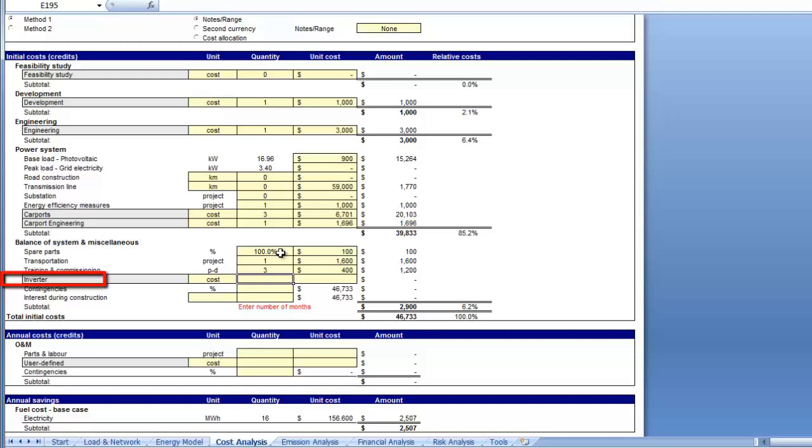Inverter pricing can vary widely depending on the type and capacity of the system, with prices for residential and commercial scale systems easily doubling the cost for large systems on a cost per watt basis. Prices can range from 20 cents per peak watt for large utility scale projects to almost $1.10 per peak watt for very small systems. Mid-size commercial scale inverters made by Chinese manufacturers and without import fees tend to fall in the range of 40 to 80 cents per peak watt.